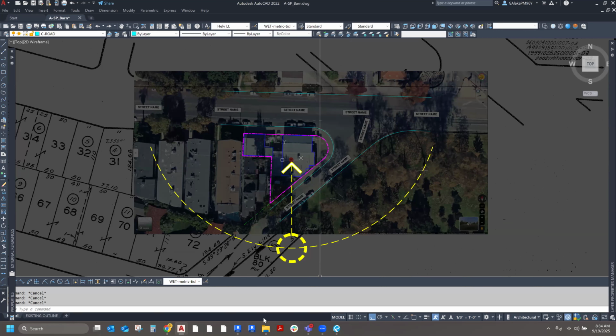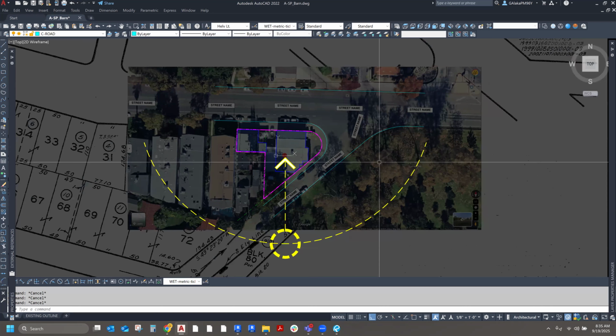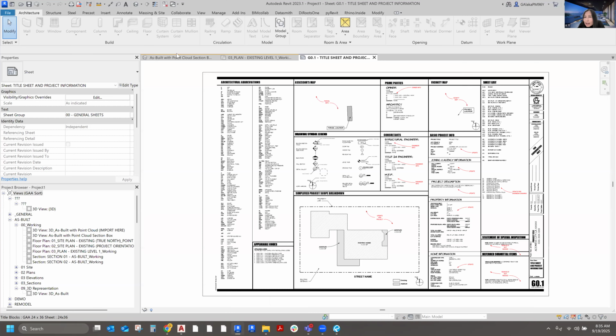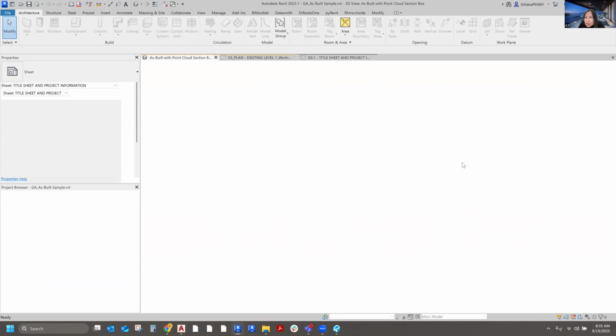Yeah, we can get the shape file, you can import the shape file, and then georeference. With the georeference you can get the Google Map background, it automatically comes together. Nice, that's good to know. Only thing is you want to know your state plane coordinate system, and if you know that one, then you can get a real coordinate too. Perfect.